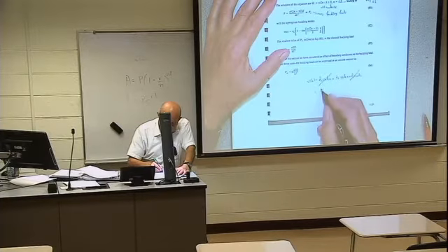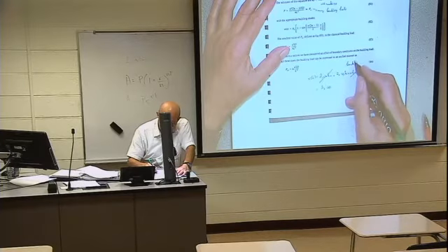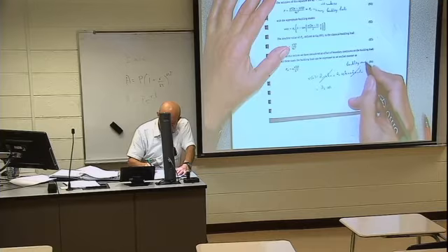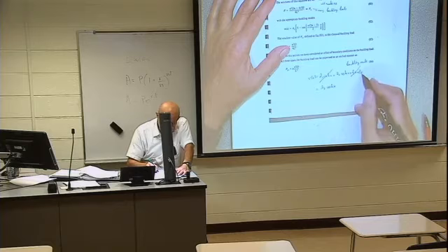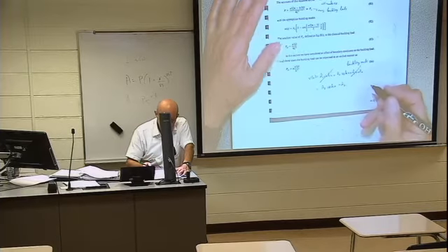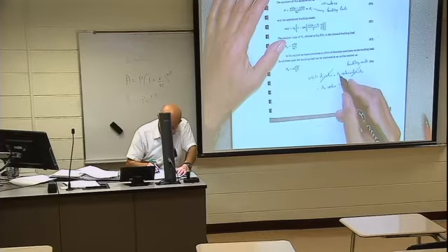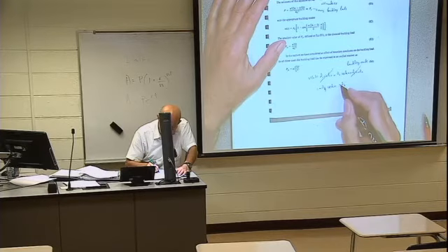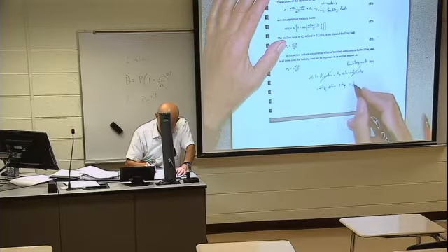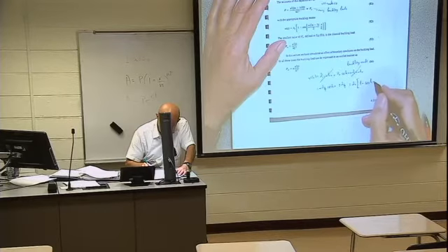So it will be a2 cosine kx, that is a buckling mode. Then instead of a4, I will write minus a2. Or maybe instead of a2, I will write minus a4, so minus a4 cosine kx plus a4. So we get a4 times (1 minus cosine kx).